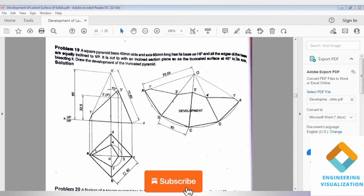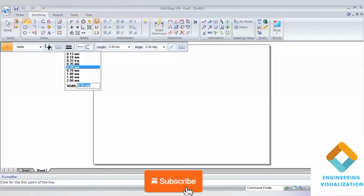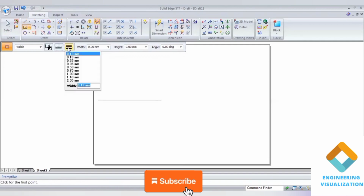So here first we need to construct a square pyramid of base 40 mm and axis 65, resting with the edges of the base equally inclined to VP. Equally inclined to VP means it is nothing but resting with the corner position. And then it will be cut by a section plane. So first we construct the top and front view of it, and then the section plane. Step by step we are going to do it, so please watch it till the end. You can understand all the steps easily.